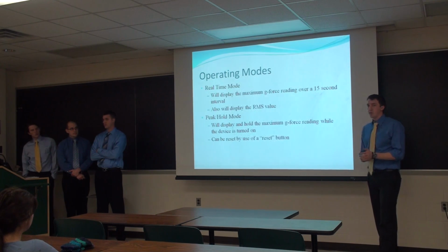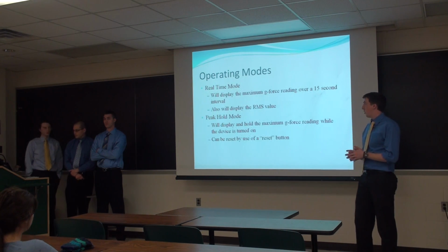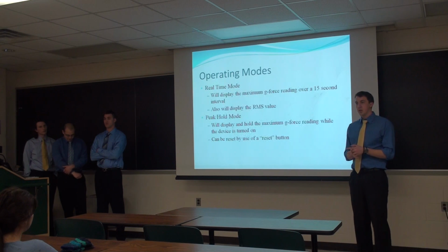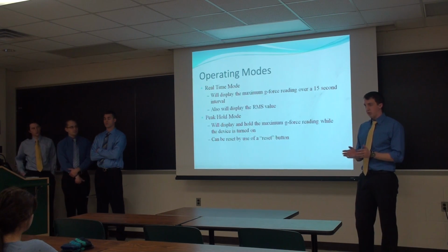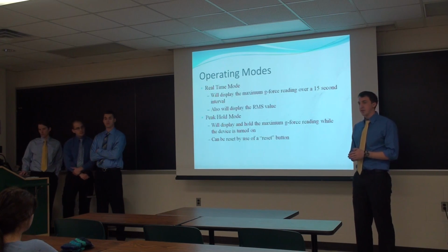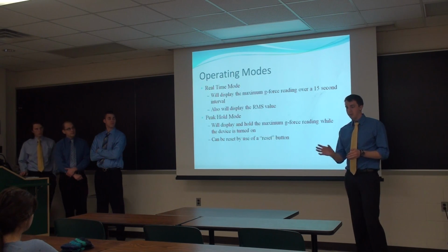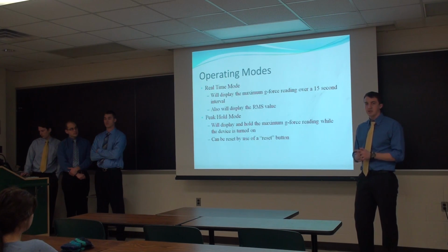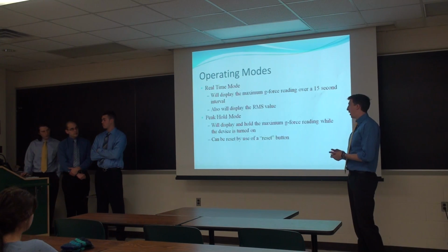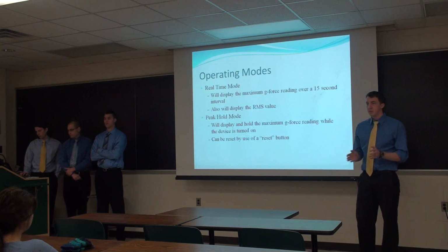So a little about the operating modes that we have. In the real-time mode, it's going to display a maximum G-force reading over a 15-second window. So the clock is going to count the 15 seconds, then over that time, the acceleration experienced will hold the maximum value just for that 15 seconds. In addition, it's also going to show the RMS value over that 15-second period.